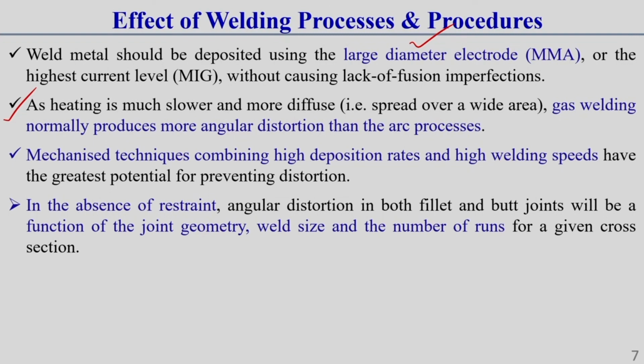During solidification, due to this wide heating zone in oxy-fuel gas welding, there is a chance of wide expansion and contraction and more deformation than in the arc welding process, because in arc welding there is a localized, concentrated heating source.